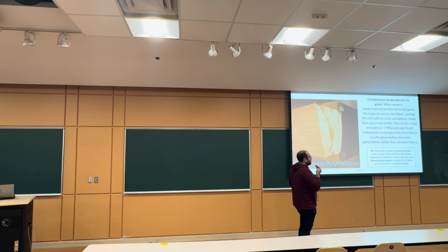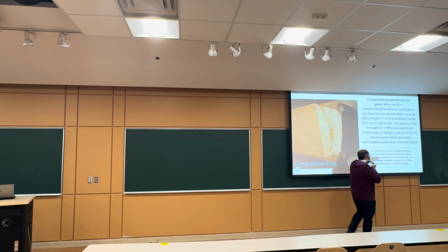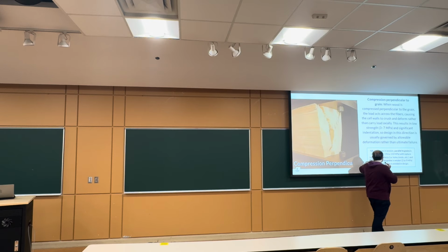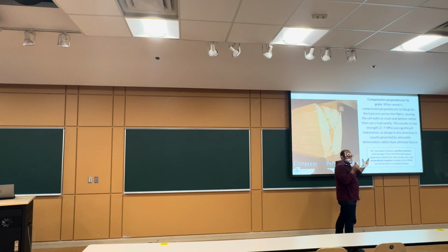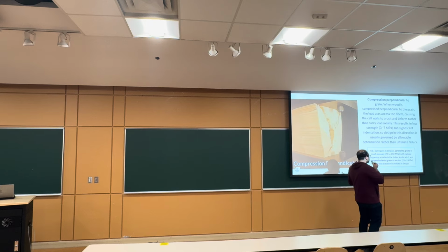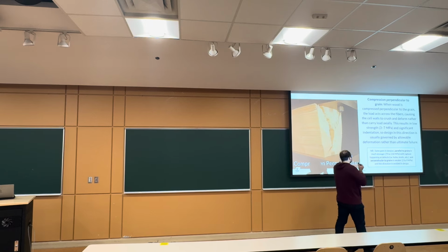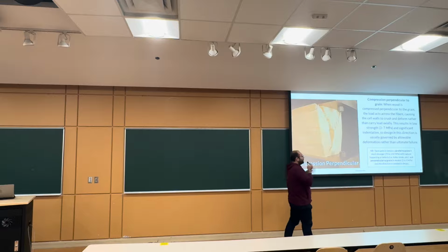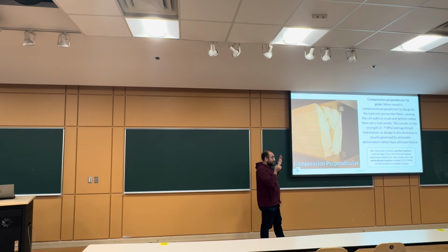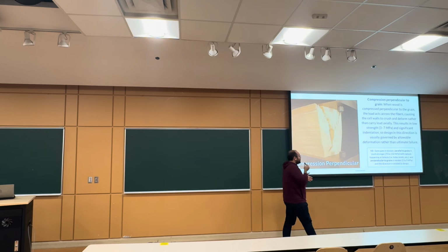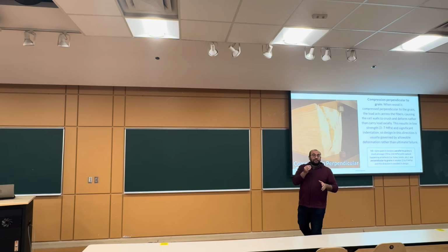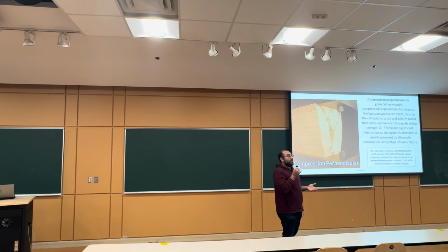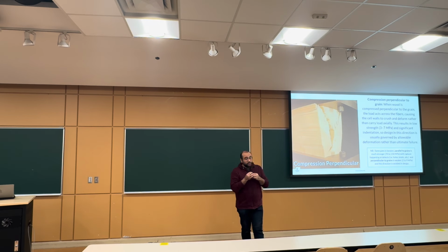Same goes in tension. Parallel to grain direction is much stronger, can reach up to 150 megapascals, with rupture happening at the defect points, such as the holes, the knots, and more, and we'll be talking about those defects in the next slides. While the perpendicular to grain is a much weaker direction, which can reach up to 9 megapascals, so the same thing goes for the tension properties, and this directionality highly affects the mechanical property of the material.